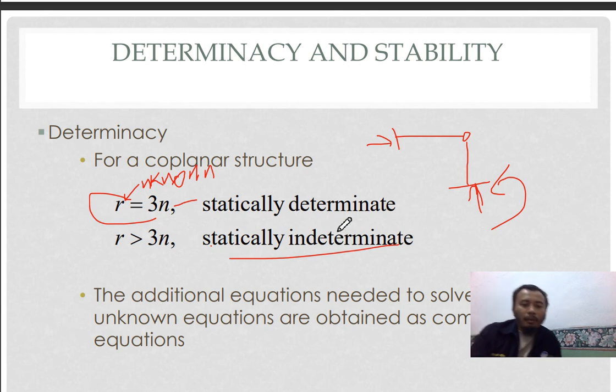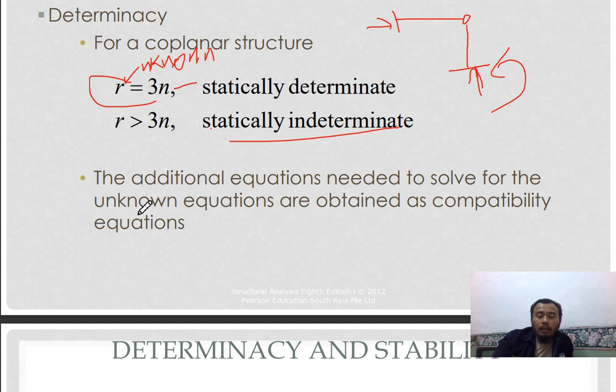So the number of members helps in analyzing the statically determinate structure. This is for information: the additional equations needed to solve for the unknown forces are obtained as compatibility equations.